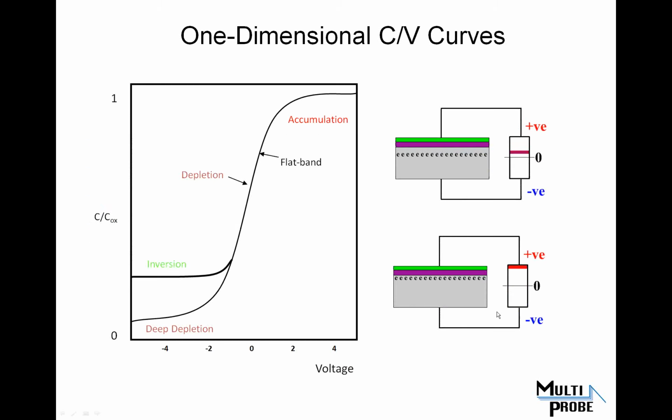So we have another diagram here which talks about depletion versus accumulation. To see how this works, the top animation refers to what's called the inversion or the low frequency depletion curve, and that is the one that's highlighted in green here. So basically, you've got a depletion, and then the inversion layer forms, and that'll be the little positive ions that form up underneath the gate. You'll see them here in a minute. Once depletion gets to a certain level, an inversion layer forms, and the capacitance doesn't change anymore.